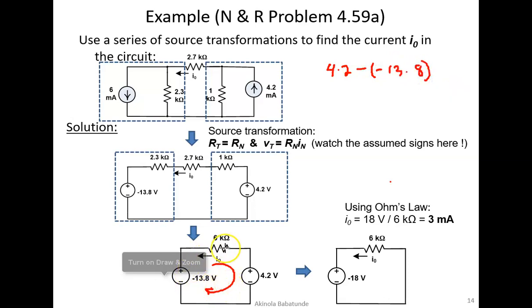And then if we are traversing this resistance, don't forget this is a positive sign, and the path of our current is actually going up here. That simply means what we're going to have here is minus 6I naught. Everything will be equal to 0 if we apply KVL here.